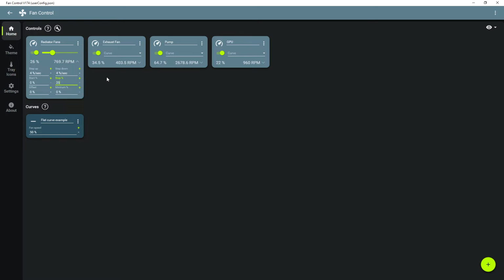So if I set this to like, you have to set this one higher first, but that's basically when this goes under this value here, it'll just stop the fans no matter what. And the start value, you can set this higher like this because say you have a set of fans that they'll run happily at like say 20%, but they won't actually get going unless you give it 30%. So basically what that will do is if I turn this down now, you'll see as soon as it hit 20, see how it drops straight to 0.